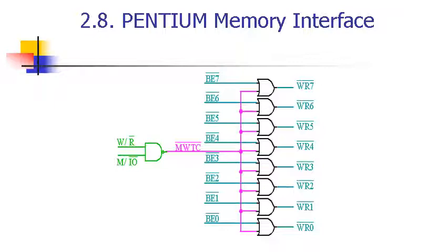Okay, here we are going to show how the write strobes for Pentium 4 are generated. So the write signal, the high write signal coming from the microprocessor, and we're talking to a memory. So the signal M/IO bar is also high. So we have the two inputs of this NAND gate are 1s, producing a low signal to activate the write cycle of your system.